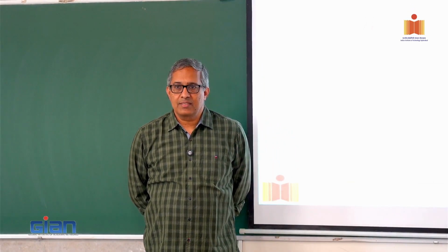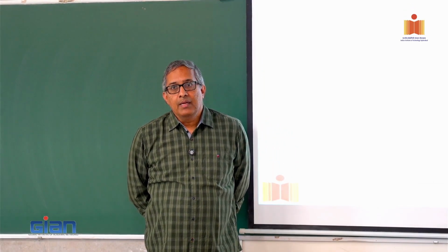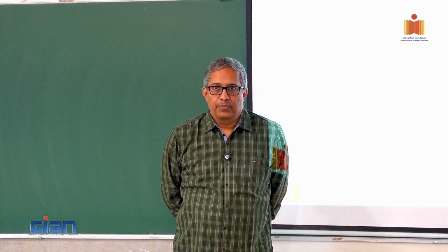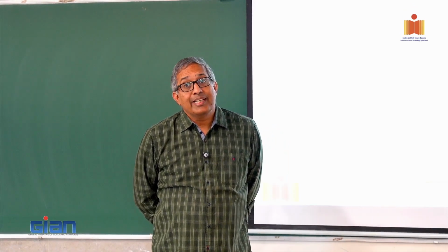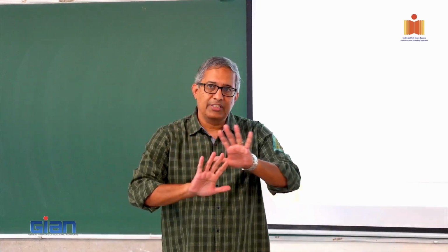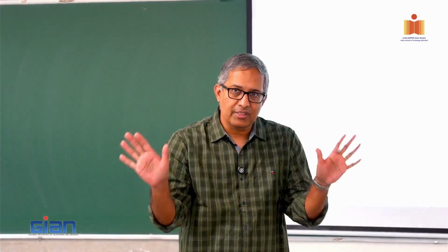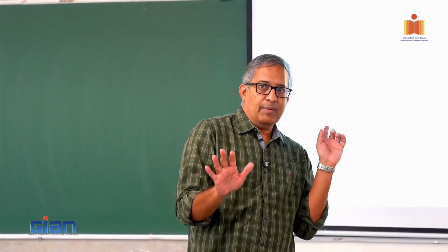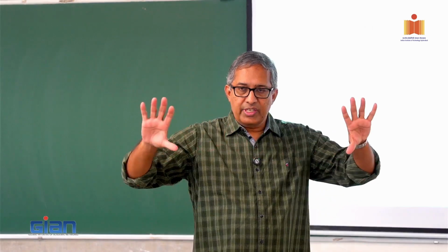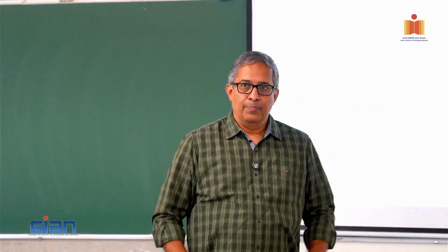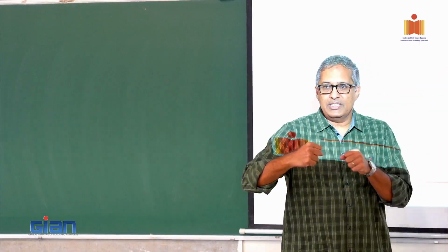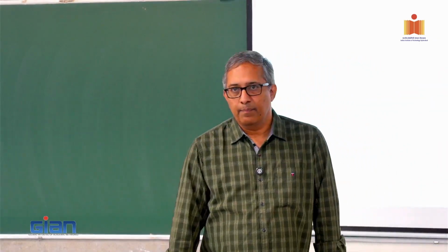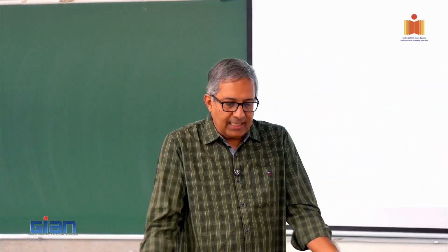What happens in a truss? How is it different from a beam? In a truss, you have 1D elements, right? The stress transfer is taken up by 1D elements. What happens in a beam? You get a two-dimensional stress field, even if you take a plane strain or plane stress idealization. So what we've done in this example is take the continuous stress field and replace it with a lattice. Then it is all about how much tension or compression a single lattice element can take. So the fundamental design approach changes.